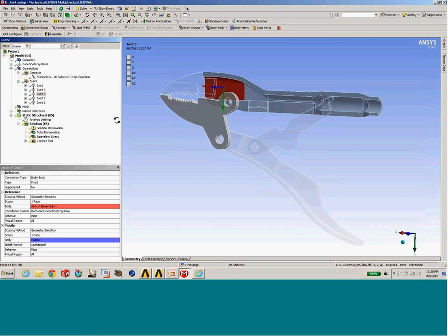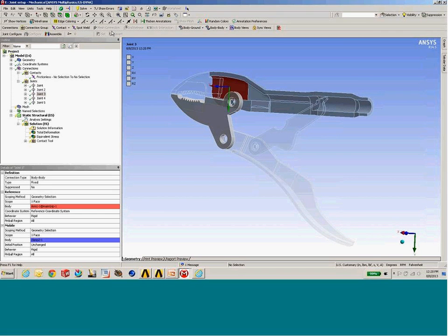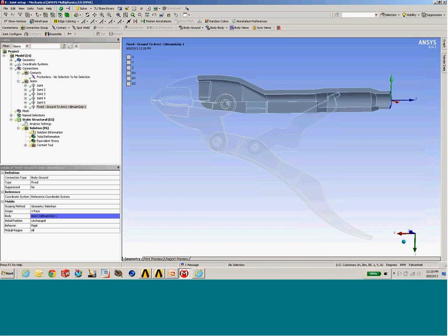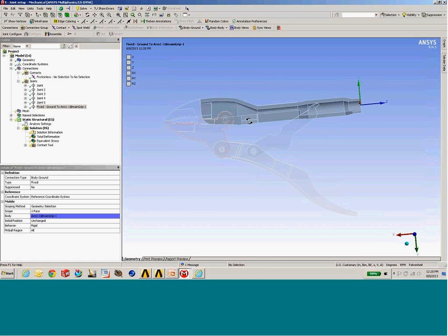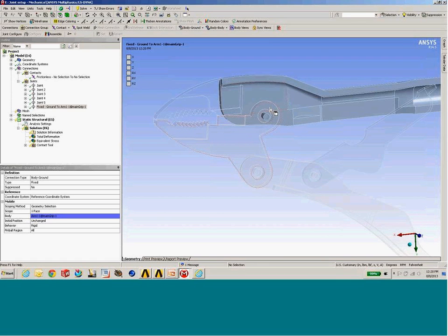So I'm going to go back now and add in that rigid one as well. So we'll pick on that face on the end there. Body to ground, fixed. And now we just need to treat these very much like we would the setup of a traditional contact scenario. We're going to go joint by joint, evaluate it, and see if it's what we need.